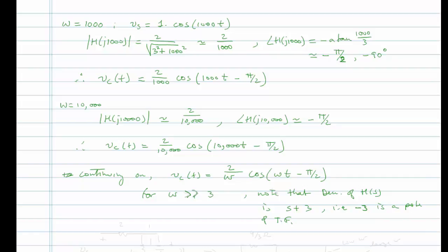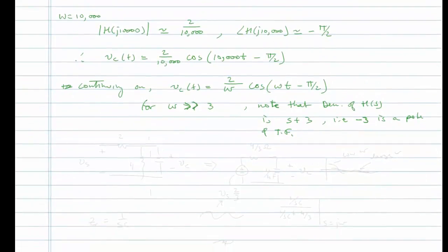Now that's some insight that you don't yet enjoy, but at least just by running these calculations over and over again for increasing omega, we see that asymptotically this is what actually happens. And so what this circuit is really doing, if I take this part right here, driving it with Vs, I could take the Thevenin equivalent, where I would have Vs times 2/3, because this is 2 and this is 4, and this would be 4/3 of an ohm, and this is 1/4 of a farad.